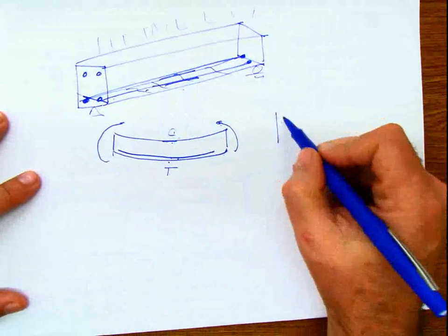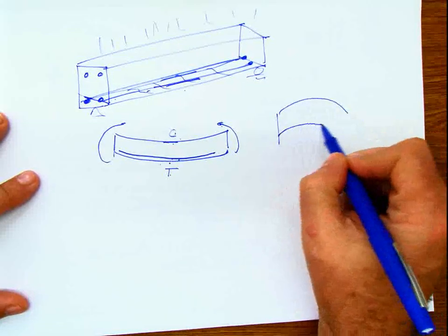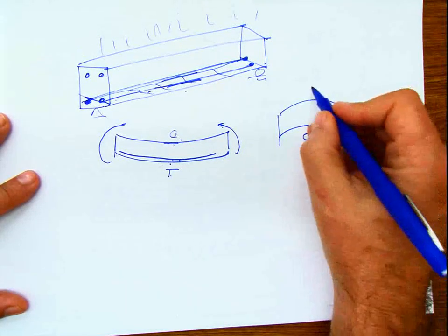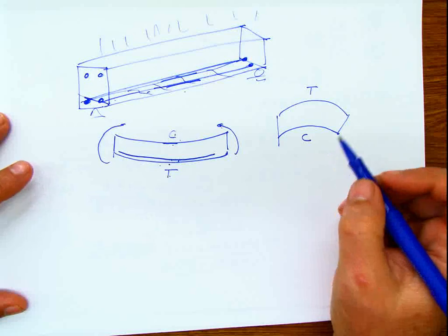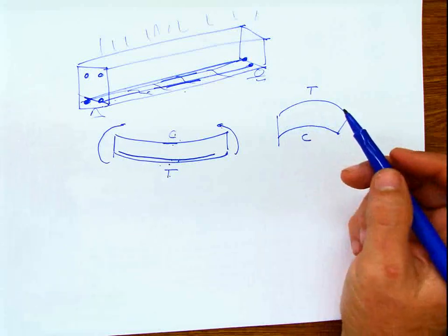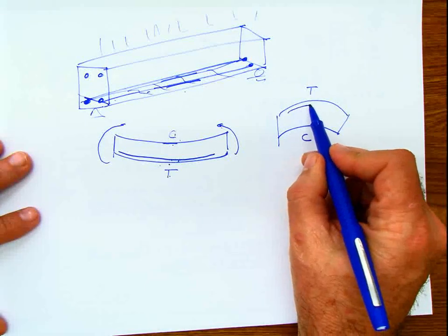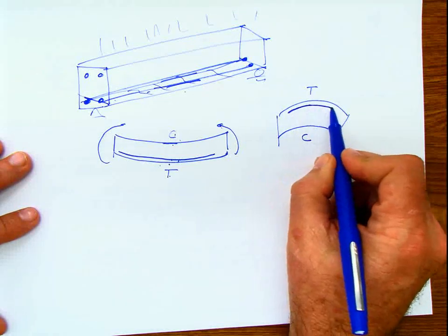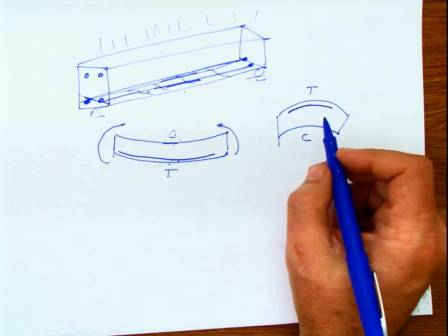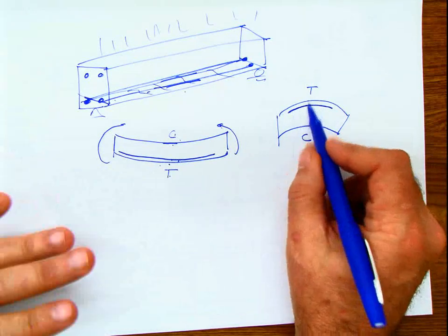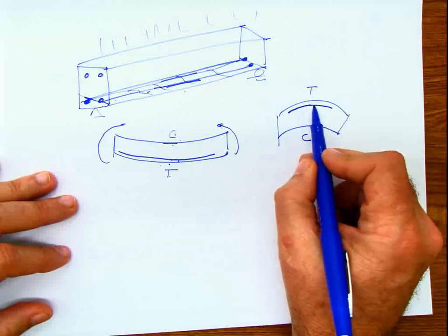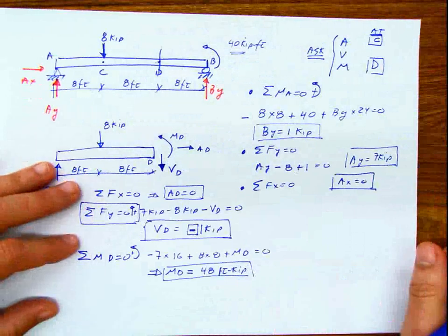Now a negative moment indicates the opposite: tension on top and compression on the bottom. So whenever you have a negative moment, if this is reinforced concrete, which is a material that is not isotropic because it varies in tension and compression, that means rebars are going to be required on the top, wherever the tension is. That's why you use the moment in that particular example.